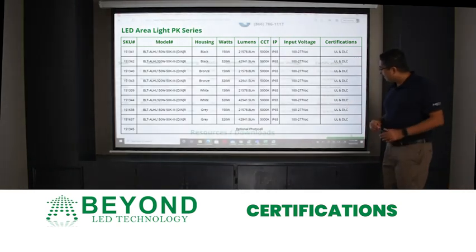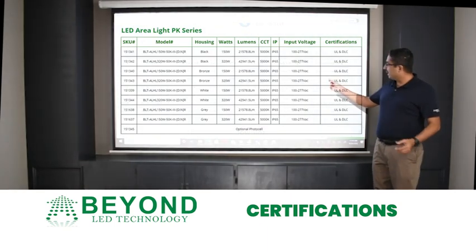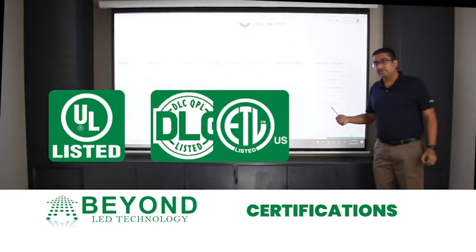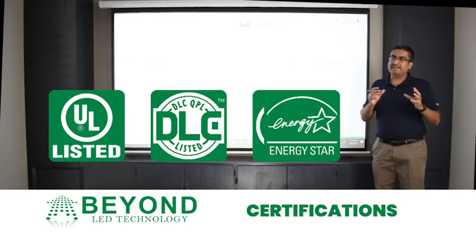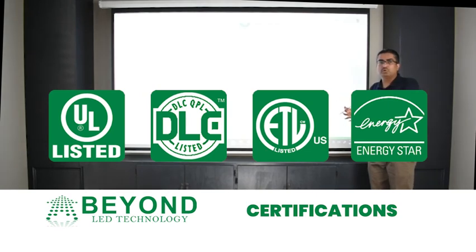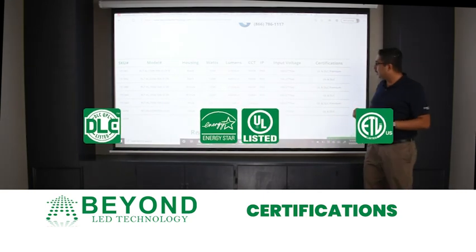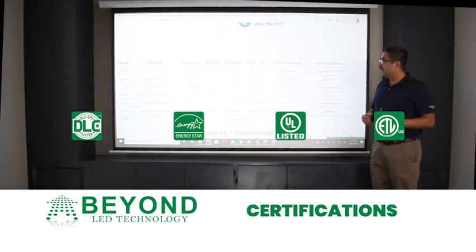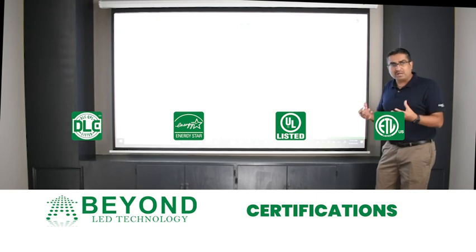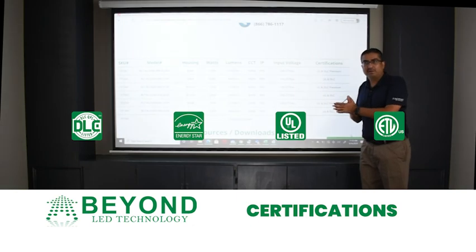Here, there are 4 types of certifications in North America: UL, DLC, ETL, and Energy Star. UL and ETL certifications are only safety certifications and have nothing to do with quality. DLC and Energy Star are quality certifications. Most of the commercial products fall under the DLC category. Some products like downlights and residential bulbs fall under the Energy Star category.